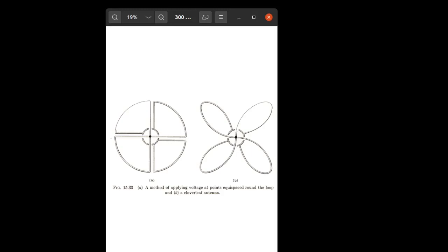For this particular design, we want an omnidirectional loop antenna, much in the sense that a monopole is omnidirectional in the azimuth. Here, to accomplish this, we return the wire. We've returned the wire from the loop back in on the drive point. The wire goes out, comes back to the other side of the drive point. Similarly here, out from one end, in and back.